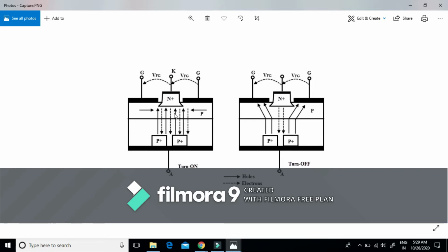This principle of operation is explained by the two transistor model analogy, just like that of SCR. In case of SCR, as already explained, the conduction starts near the gate terminal, whereas GTO consists of various narrow elements with gate terminal.